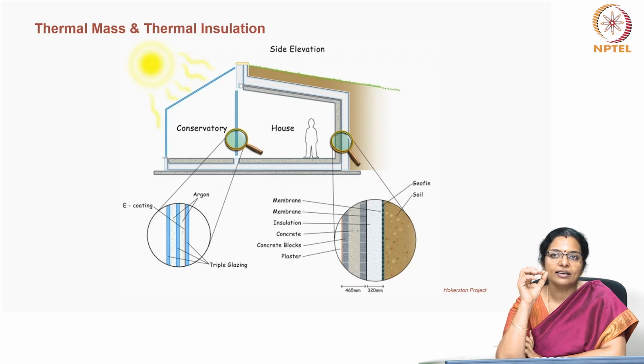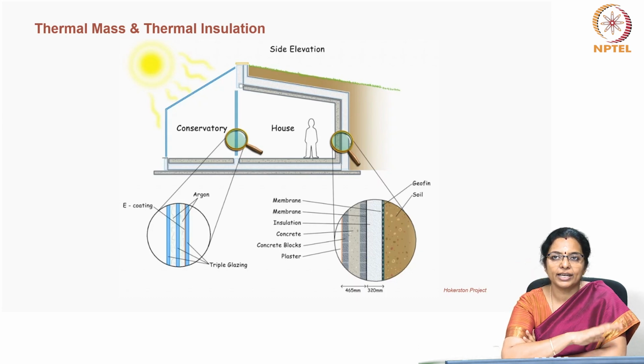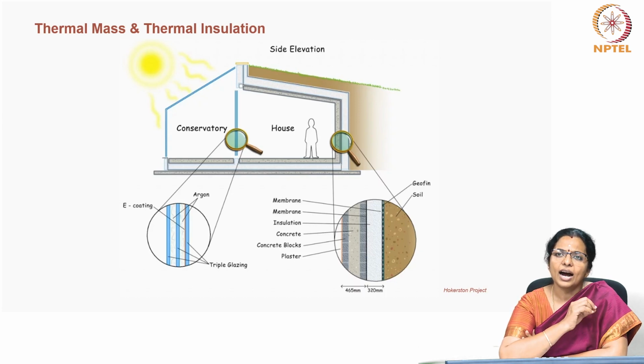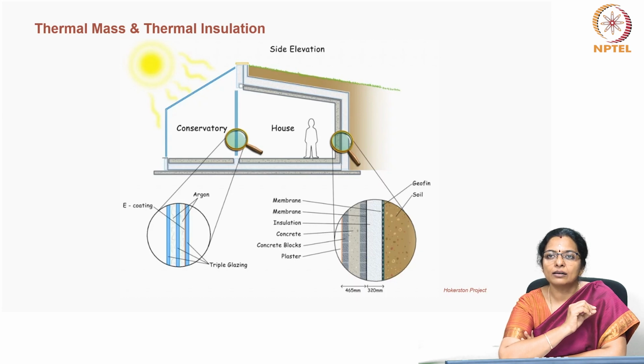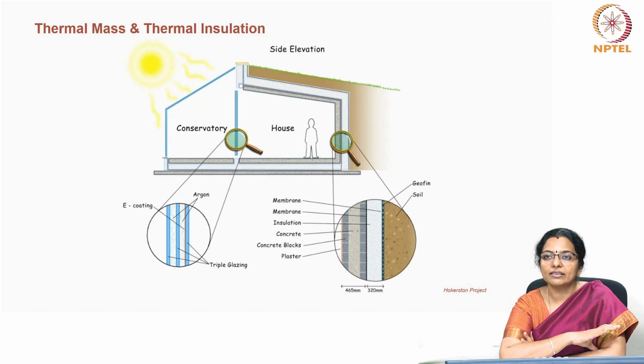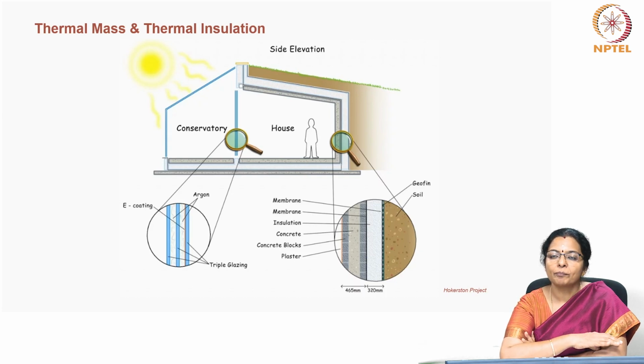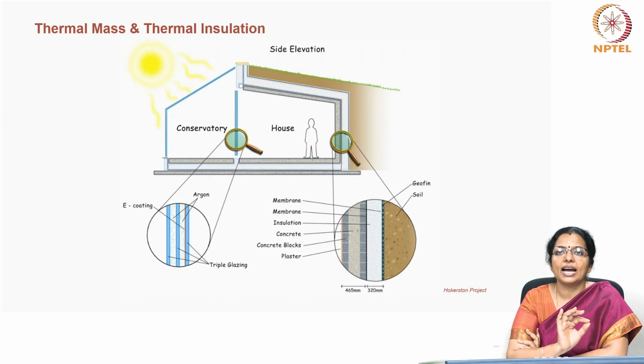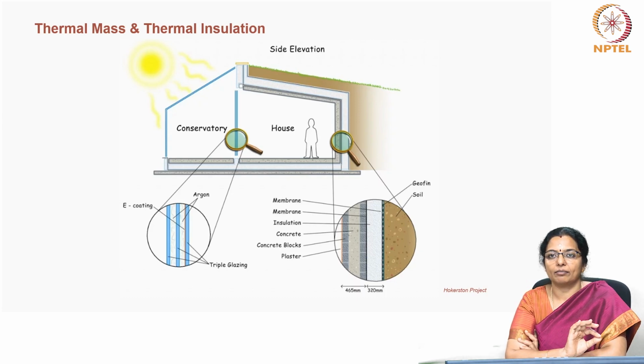Solar gains heat the thermal mass by day. It releases warmth at night for heating. Conversely, effective cooling requires nighttime release of stored energy. Natural ventilation emerges as a key strategy for efficient energy release. Understanding and harnessing the thermal mass of building materials is essential for optimizing passive heating and cooling methods, ensuring an energy efficient and comfortable indoor environment.